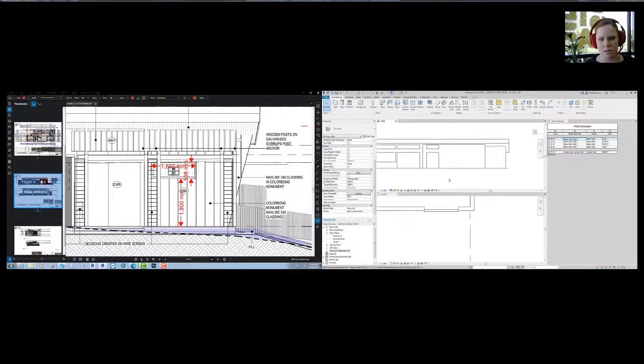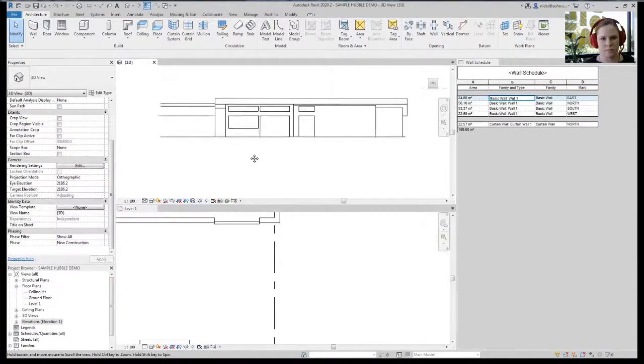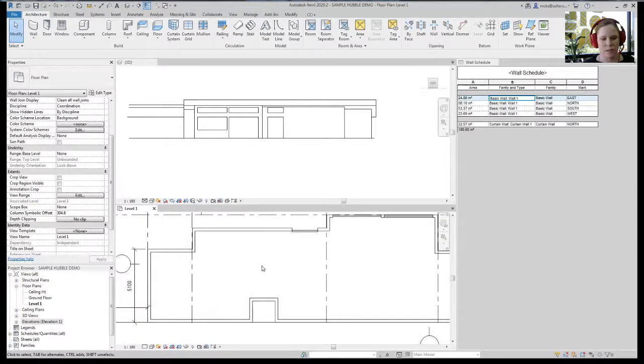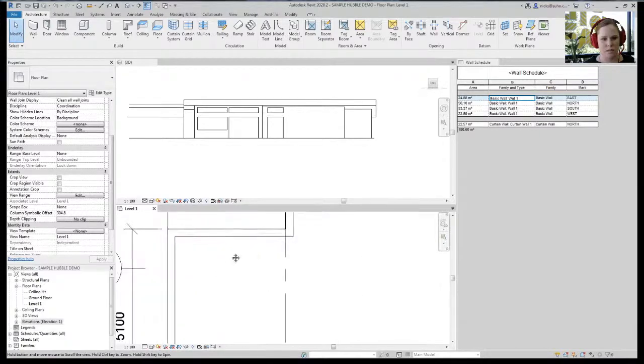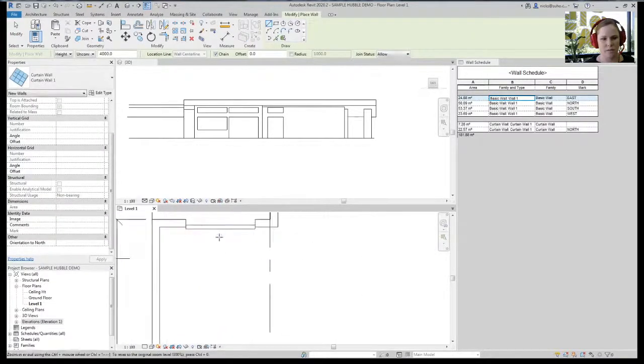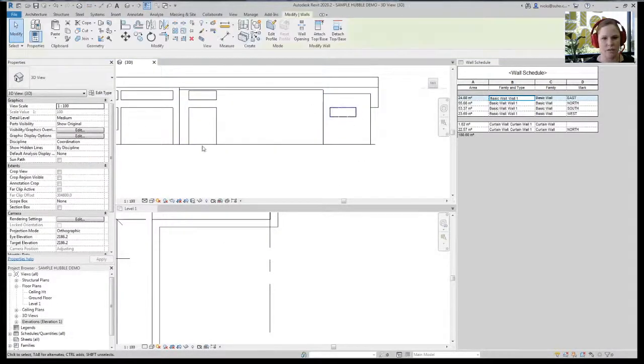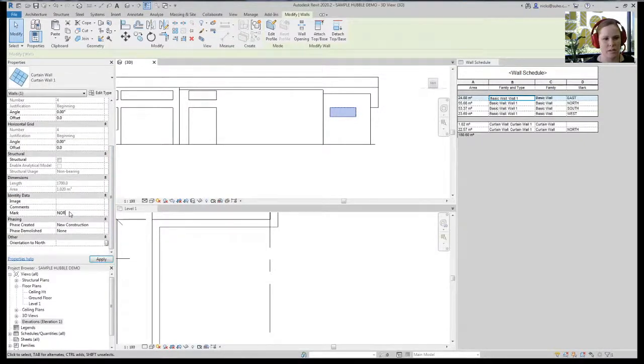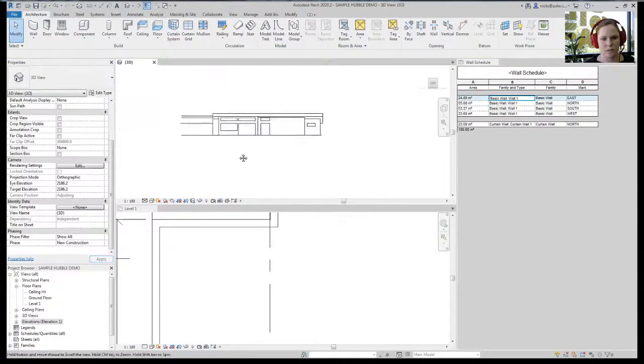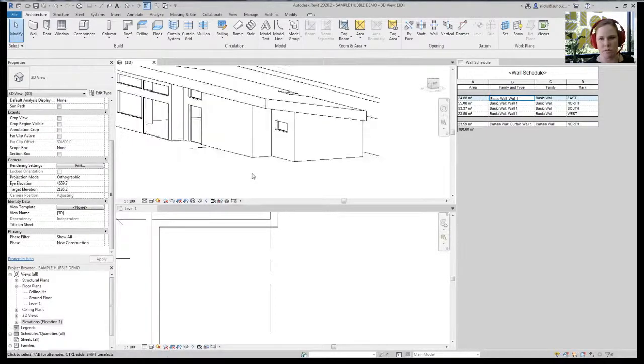Okay, so I'm going to put these values into my model now. And then also in the bed, take the values from that, change it. So the height of the window is 600, and it's offset 1800, because we've got a nice high ceiling in here, it's raked. Okay, give us its orientation again, north. Okay, so that's all the northern glazing, but as you'll see as we go around and do the other glazing and we'll group them, you'll see the table on the right change.